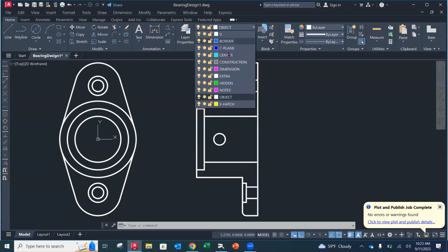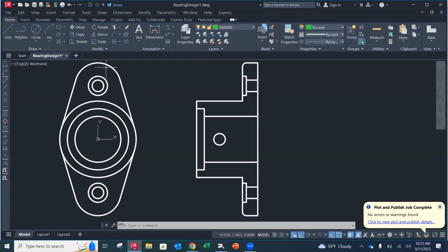I'm going to go to the hidden line layer. I'm going to go line here, grab that quadrant, go over. Okay. And notice I grab that intersection, and then this one doesn't want to do it. So I'm going to intentionally go past it and then trim it, because I think it might grab a tangency line. I don't want that to happen. Okay. I want to go straight through. Same thing for the other one.